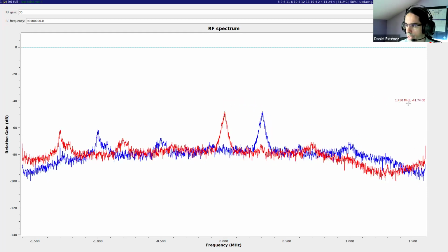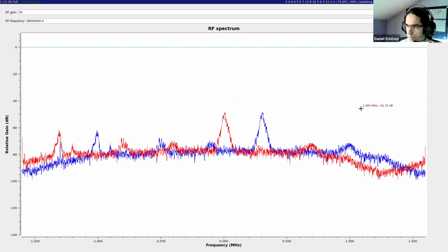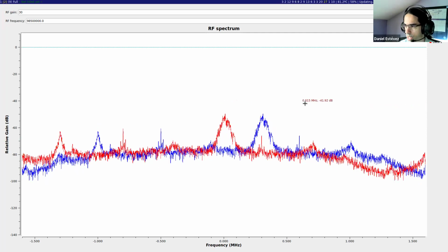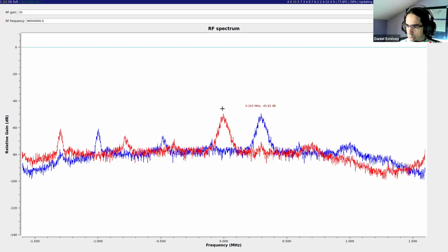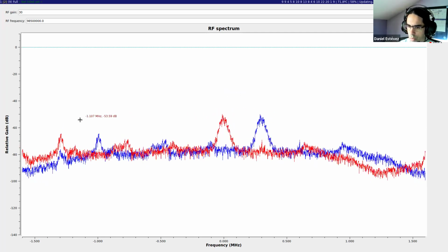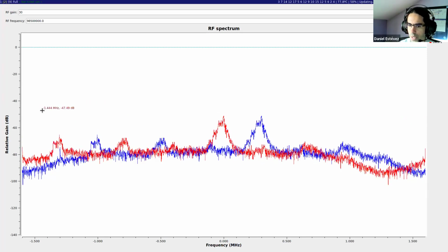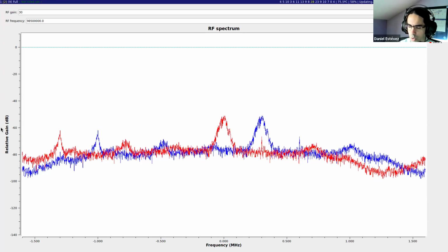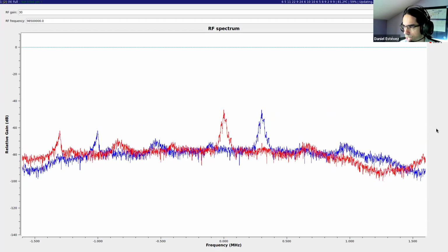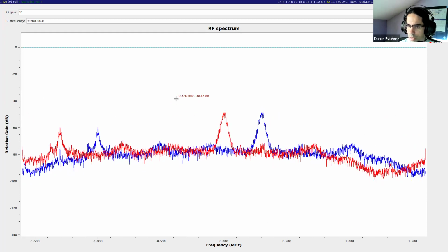With real sampling, we saw that when we reach the right half, things start mirroring down. So we go like this, and then we mirror down, and then we kind of rebound at 0, and we keep going like this, back and forth. But complex sampling is somewhat different. When you go through this edge, we appear on the other edge, and we can continue indefinitely. But going in one direction, it's the same. If we shift it to the right, everything which goes out of the right edge will appear again on the left edge. So hopefully that is clear.